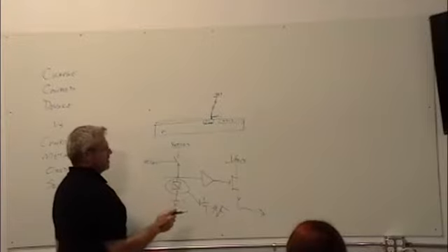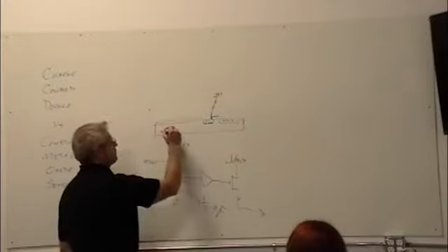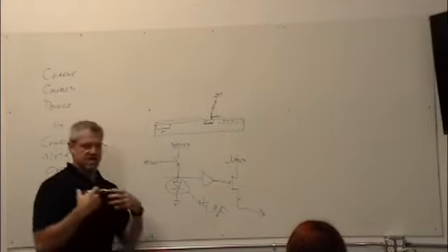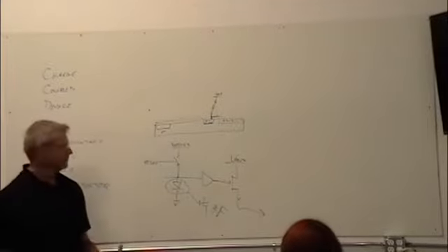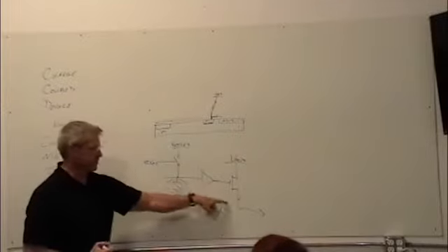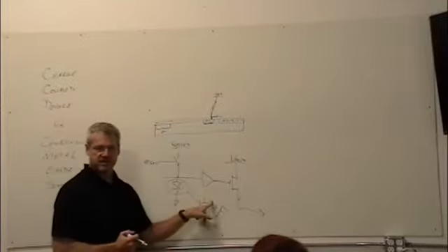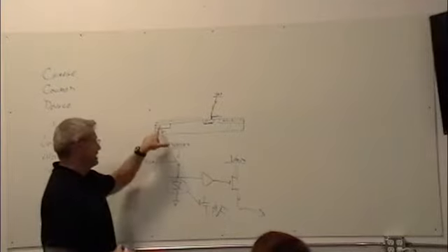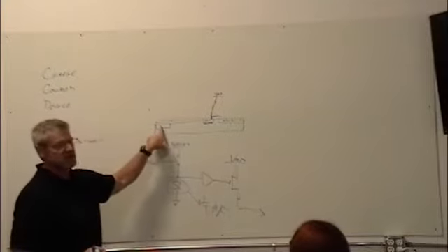And then what you say is, however deep this well is, however many electrons it can hold, then you can figure out volts per electron, because this is never going to go above about 0.6 or 0.7 volts. And a really big well is maybe 150,000 electrons.